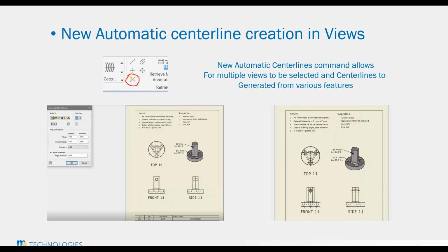So some interesting things there and how this picks up, but again, it will just quickly cascade and put your center lines in there. There is a command that actually allows you to extend the center line mark outside the geometry. But again, it just quickly throws this information in there and you're able to dimension to it. So if you were to do this one by one, it would probably take you quite some time to quickly put all these center lines in that are needed.